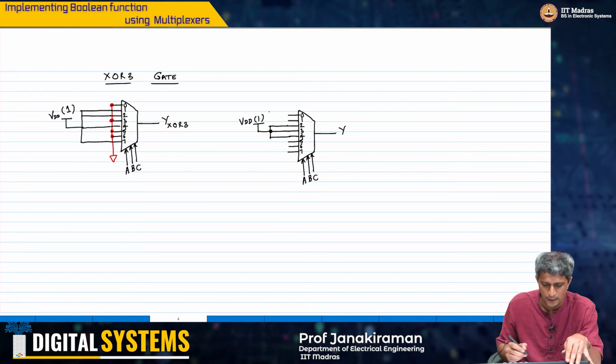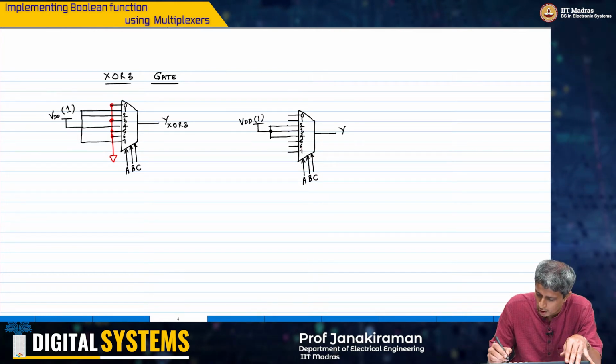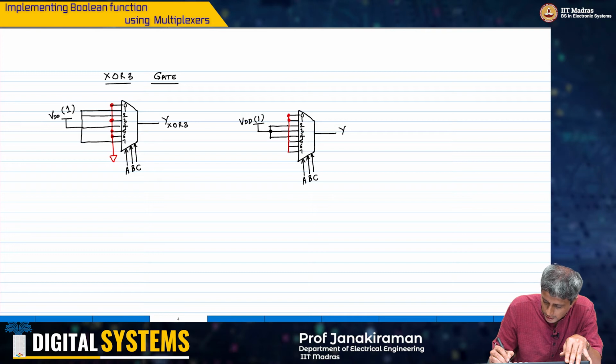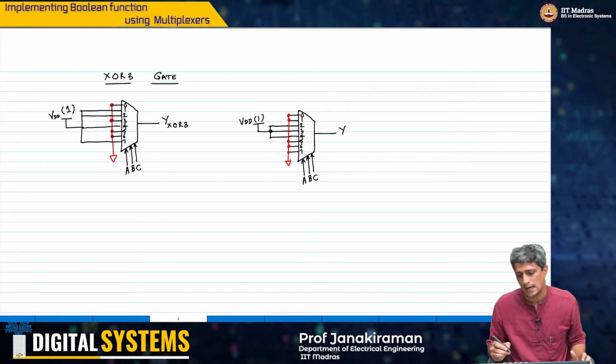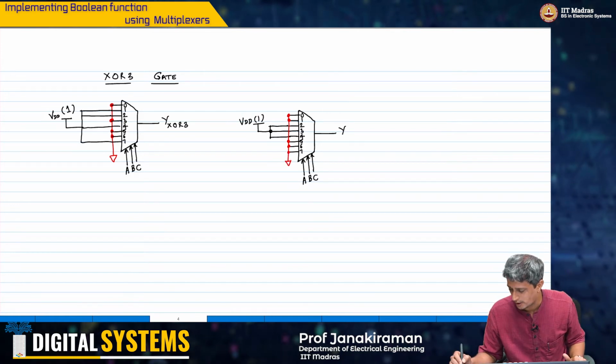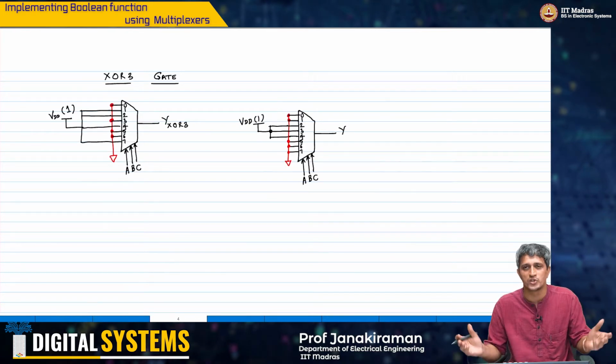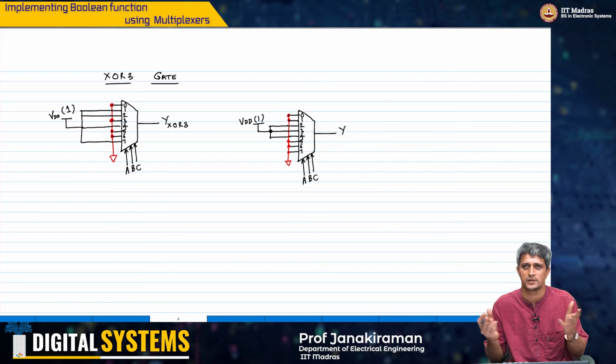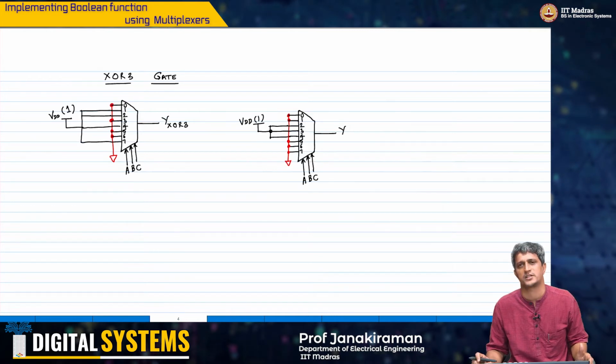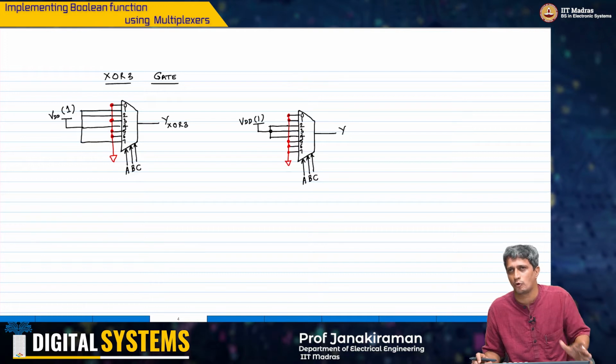One, okay, and then I am going to now simply connect the remaining signals here, 0, 1, 5, 6, 7 to ground like this, and I will get the implementation for the signal y, okay. So like I mentioned, it's not possible to reuse any gates here or optimize the number of gates. It's just a different implementation. You basically need one multiplexer per output, right?